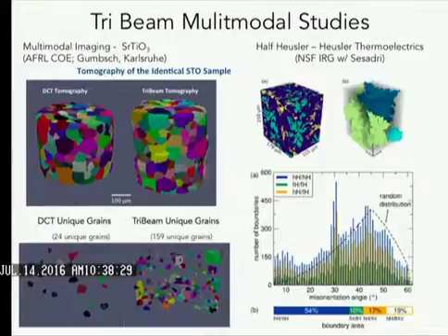So here's one other sort of example from that list of reasons why you would do this. This is a thermoelectric, which is obviously of interest for harvesting waste heat. These Heusler intermetallic compounds are interesting because their figure of merit peaks in sort of the range of temperatures where most automotive or turbine engine exhausts would be exhausting air. And so the idea here is to combine these two structurally similar crystal structures to get lots of boundaries so that we can lower the thermal conductivity.